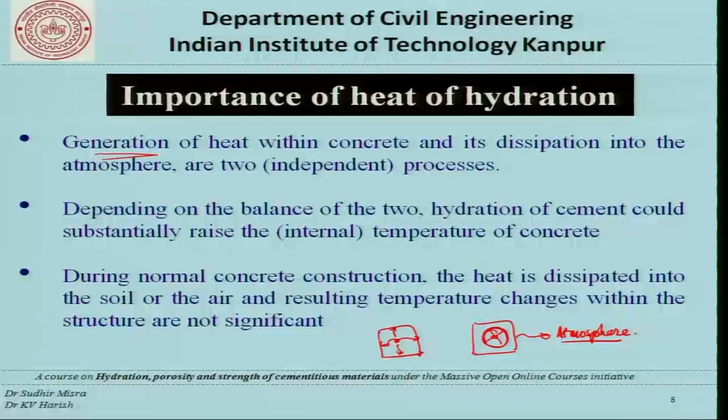This dissipation is more or less an independent process and has to be looked upon independently from the heat generation process. Depending on the balance of the two, heat generation and heat dissipation, hydration of cement could substantially raise the internal temperature of concrete.